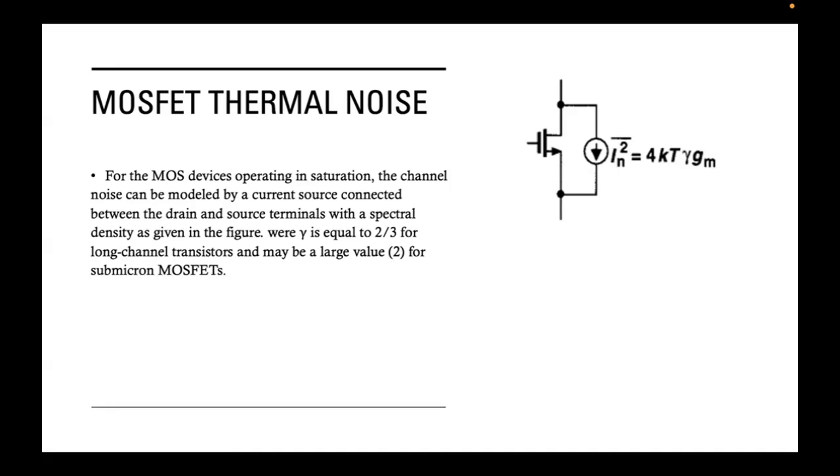In transistors, we have two types of noise sources. The first is simply some sort of resistive thermal white noise. If you consider the path from the drain to the source under the saturation region, this mainly applies to the saturation region, because you know that most applications of transistors, either analog or digital, are in the saturation region. That's why we are going to focus more on the saturation region. So in the saturation region, we can consider the current path from the drain to the source, or actually the electron flow from the source to the drain.